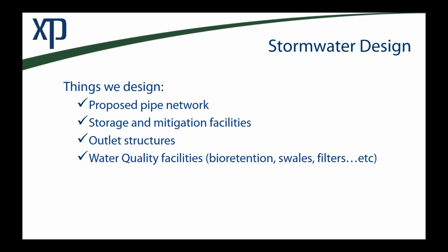Another item, we could have water quality facilities, water quality storage. Okay, now that is pretty well the fourth thing that we're doing on every project now. Certainly new development, almost everywhere in the U.S., that is a requirement to implement these green facilities, bioretention, swales, filters, so on and so forth. So certainly traditional design, I'd call it: a pipe drains into a pond, there's an outlet. Really where we are now is we're doing retrofits to incorporate water quality systems, or any new design, you have to have water quality in addition to your traditional drainage system.